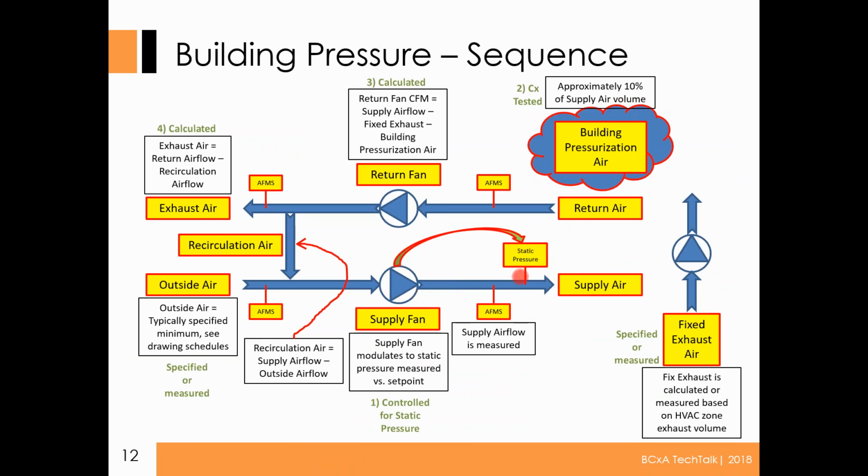This gets set up if you've done a good job, worked with the balancer. You say, I need my 2.3 inches for this system, so the furthest VAV box on max cooling has enough air. This is sort of fixed. The speed of the supply fan, the amount of CFM of the supply fan is fixed. What this question is referring to is the return fan side, and I think I'm going to simplify it and say the tracking between the two of them.